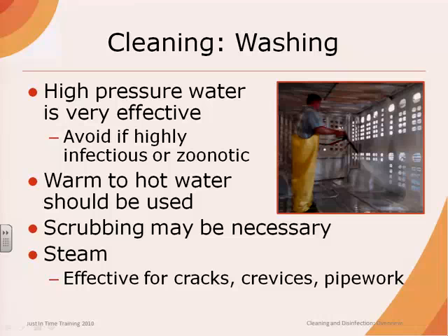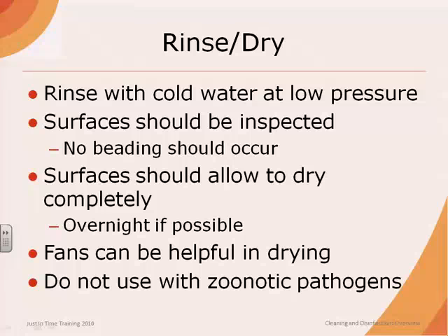Hot water and steam can be effective for cleaning cracks, crevices, and the inside of pipework where pathogens are likely to linger. After washing, all surfaces should be thoroughly rinsed at low pressure with cold water. Surfaces should then be carefully inspected to ensure they are visibly clean.